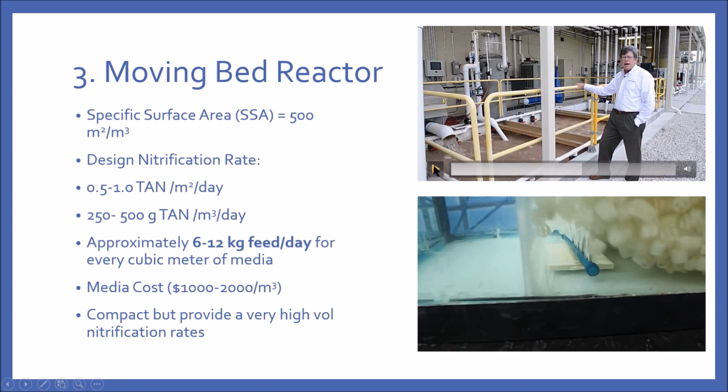So what are the nitrification rates of this moving bed reactor? For every cubic meter of media, you can process up to 6 to 12 kilos. Why 6 to 12? 6 is when you're applying it in salt water, and 12 when applying it in fresh water. As you can see, the media cost is relatively expensive, much more expensive than sand or pebbles. However, it provides very reliable nitrification.